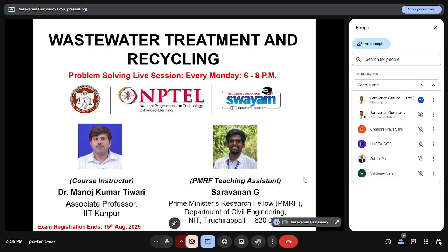So in the first week we discussed a brief introduction to wastewater treatment and recycling, and in the second week we discussed the sources of wastewater and how we can classify wastewaters. In the third week, we discussed the physical, chemical, and biological parameters of wastewater, like pH, turbidity, color, and chemical parameters like alkalinity, hardness, BOD, COD, dissolved oxygen, and biological parameters like coliforms, that is the fecal coliforms, and in the chemical we had nutrients, metals, heavy metals. So this week we are going to discuss the treatment process.